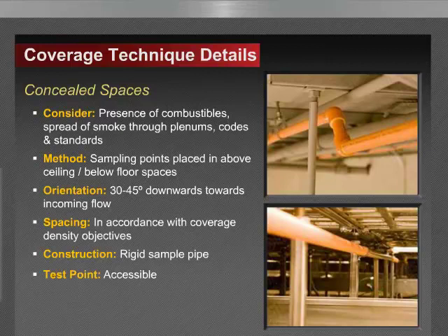Plus, this will prevent buildup of dust and dirt at the location of the sampling port. So sampling ports are spaced in compliance, again, with the sensitivity objectives for the space. And again, that is the standard fire detection, early warning fire detection, or very early warning fire detection scheme.